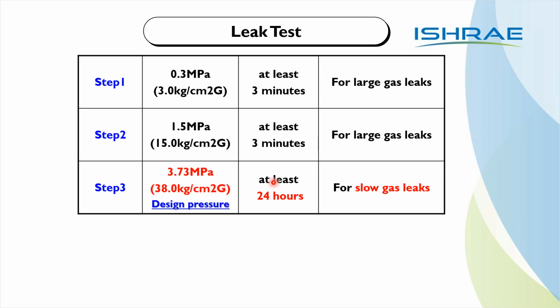Now, for the minimum gas leak pressure testing, what you need to do is hold it for 24 hours. Here also, never ever compromise. The customer will always put pressure on you. He will say, tomorrow I have got the inauguration of my store. Tomorrow I have got a housewarming ceremony. Tomorrow I have got the opening of my hotel.